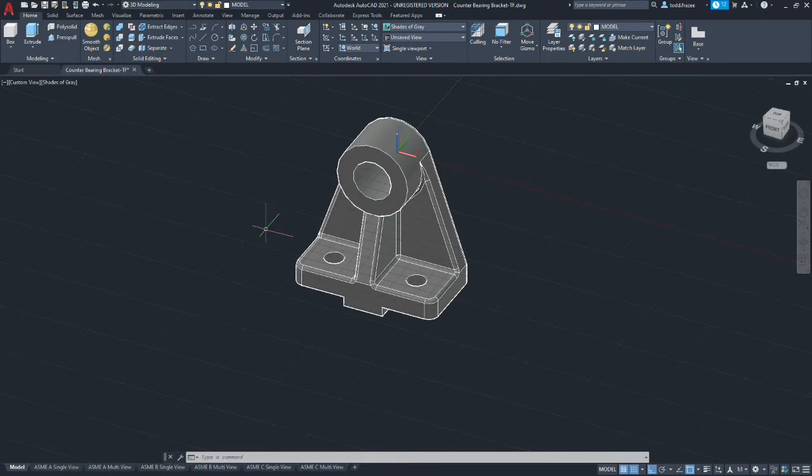When you view your model, be sure that the profile that represents the front view is parallel to the plane formed by X and Z when we're in world coordinate systems. If you have to, rotate your model so that it is orientated similar. Placement of the origin is not critical for this, but the orientation of it is.